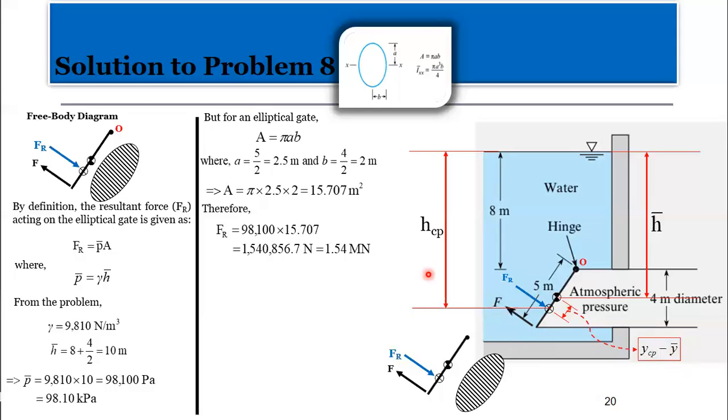So let's first of all obtain a general formulation for F, okay? To find F, we take moment about point O such that the clockwise moment about point O is 0, and the anti-clockwise moments are positive, right? So that's F times 5. Look at something here. This is the hinge, right? If I pull F, it turns it about clockwise. So here is positive F times 5. That is why we have a positive value.